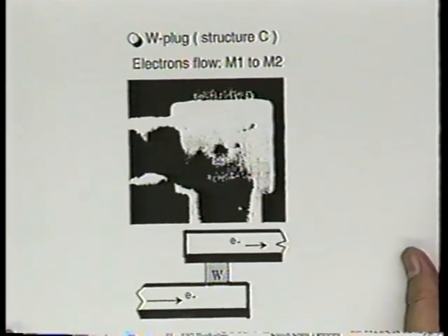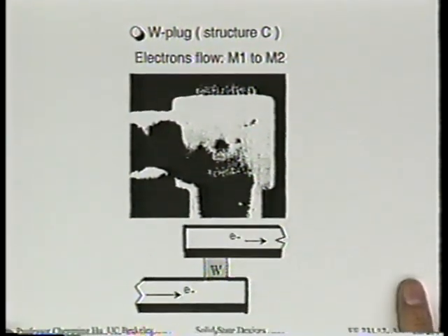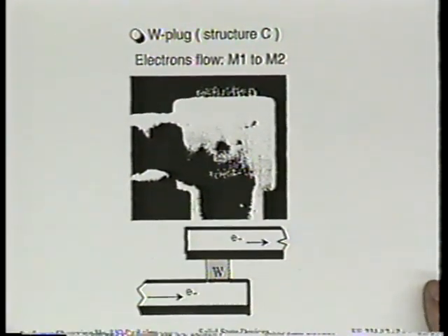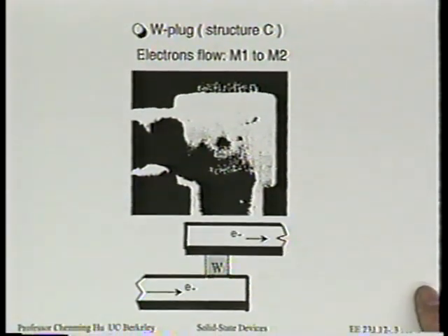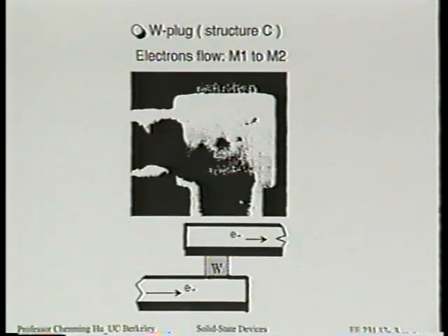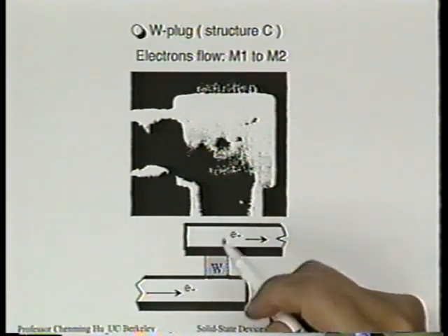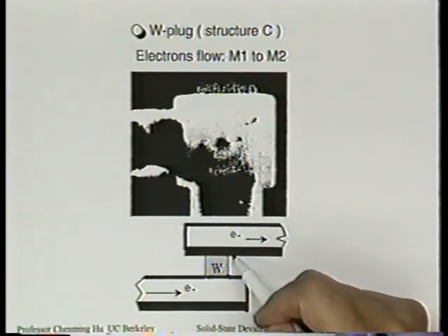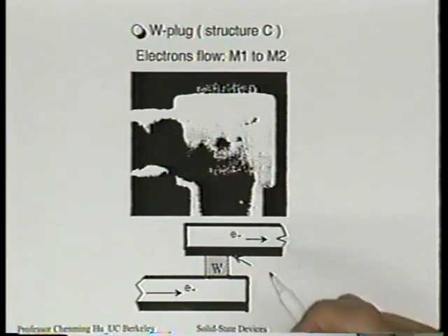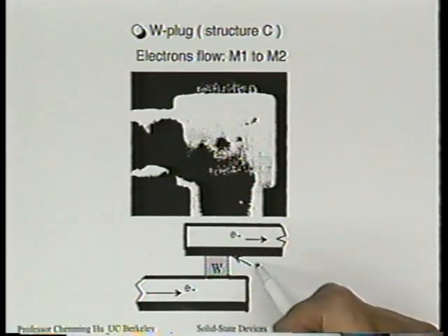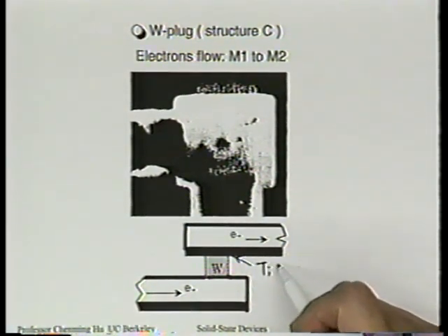Well, turns out one thing to improve that, and this is how everyone does it now. 5 years ago, 10 years ago, wasn't like that. But now people have learned the thing to do is don't just put the tungsten directly in contact with aluminum. Instead, put a layer of material. Very often we put a titanium layer, let's say titanium nitride, for example.